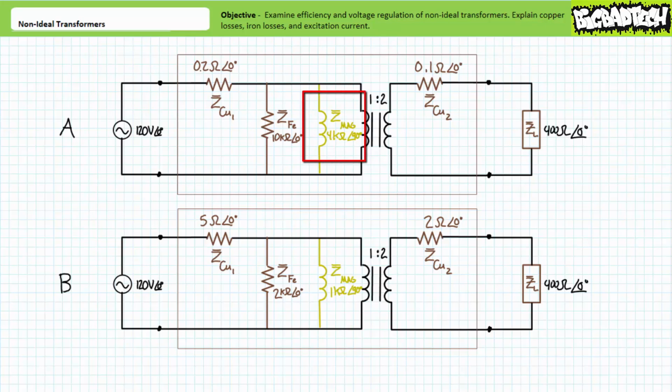Finally, the parallel inductor accounting for both magnetizing current and hysteresis also has a larger magnitude, and as such will draw less current, meaning Transformer A necessitates the consumption of far less reactive power to operate than Transformer B.